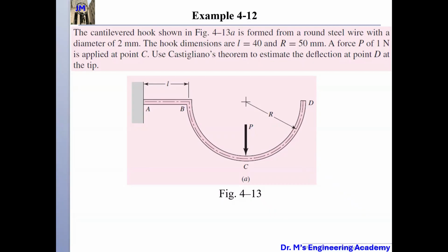And this one, okay, this is U. As I said, we have 3 flat segments. So this is U, and then delta equals dU1, U2, U3, divided by Q. Right? So U1 is the strain energy for this segment, U2 is the strain energy for this segment, and U3 is the strain energy for this segment. Do you guys agree? So this equals dU1/dQ plus dU2/dQ plus dU3/dQ.